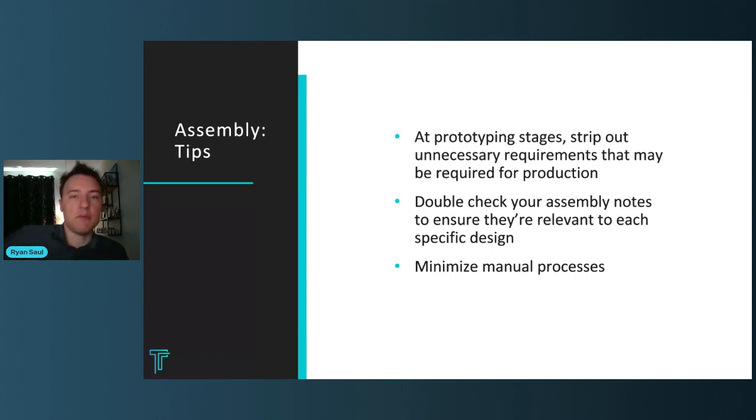An example of a manual process would be what you call blue wires or some sort of necessary rework. We see this oftentimes with some of our customers that have very low flexibility in their design, meaning they're perhaps prohibited by their internal company policy to roll the rev, but they know their design is wrong. And so they just want us to build it from scratch, but then also do rework at the end. And as an engineer, it's a little bit frustrating, of course, to know, why don't you just change the copper trace, and then you don't need this wire at the end of your run.